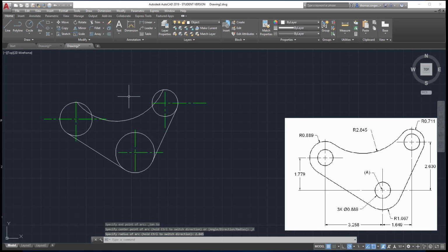Oh, that didn't go as well as I would have hoped, right? Because that's what most people would do, they go to the arc command. And the arc command has start end radius, and we use tangents just like we did with the lines. Makes perfect sense, except it never works. Because the tangency positions, if you recognize that, it was a single position location. And so we're going to have to delete the arc here. So we just go up and pick it, grip it, right mouse click, and choose erase.